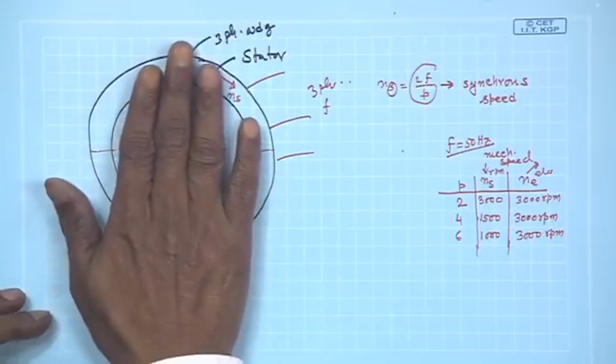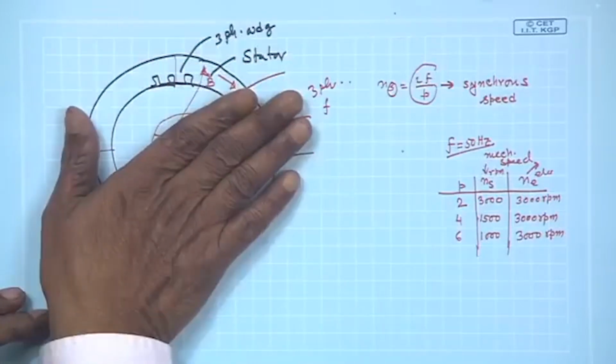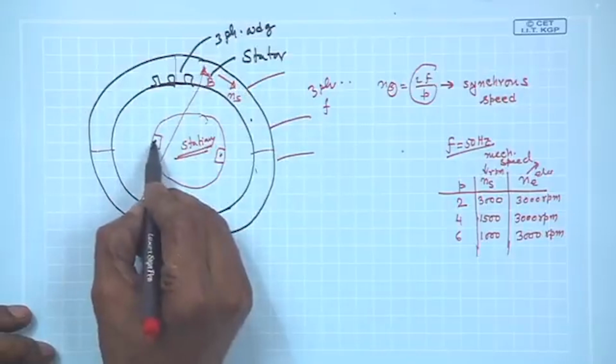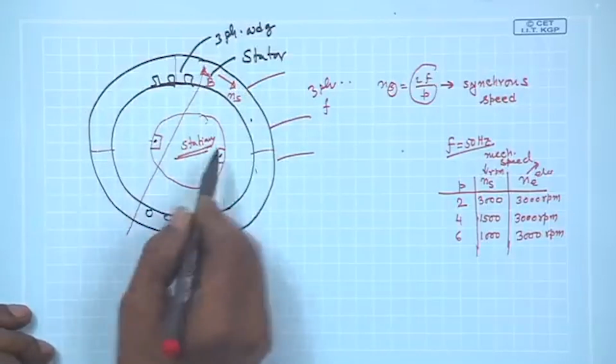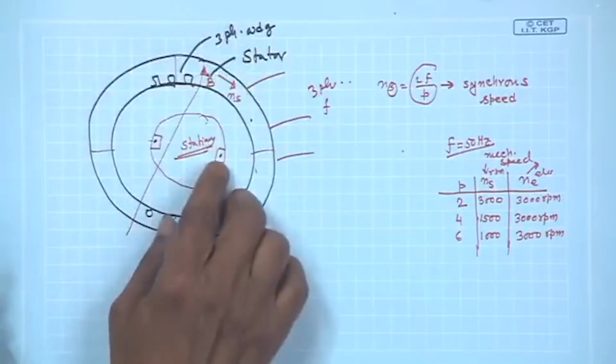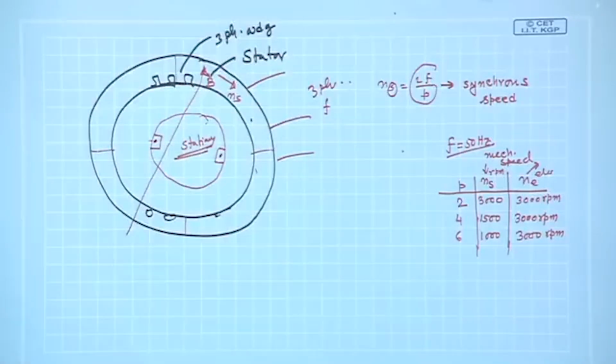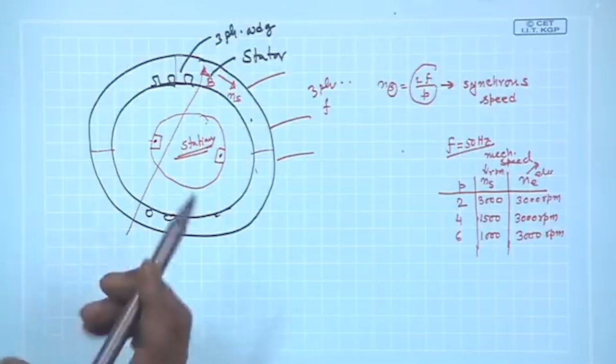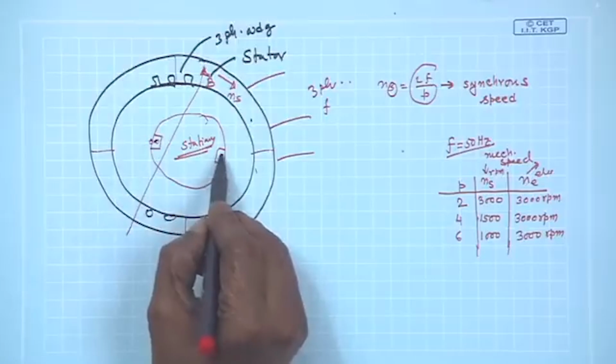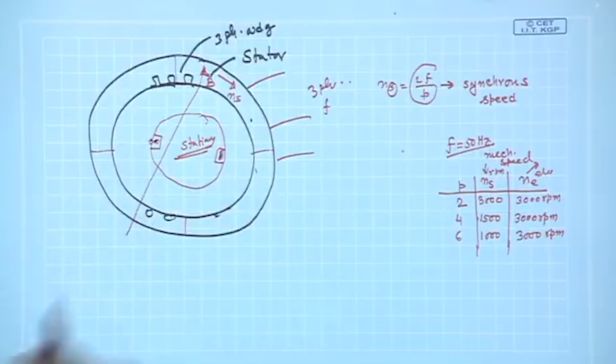Now, as this rotating magnetic field is existing, there is bound to be induced voltage here in the coils, because the flux linkage of each conductor comes under north pole, south pole, BLV is there, all these things we now know. Now, the question is, what will be the magnitude of the voltage I want to calculate in these rotor coils?